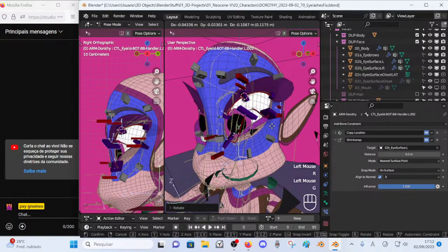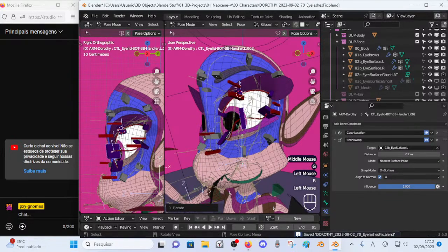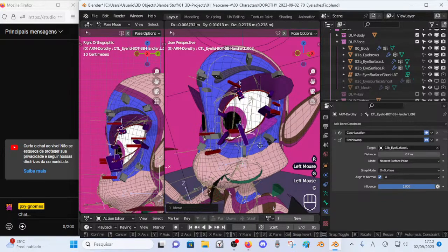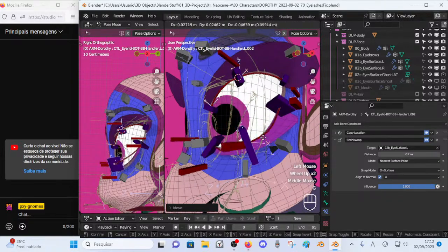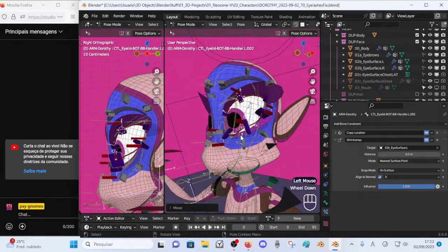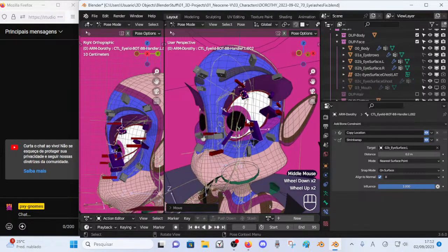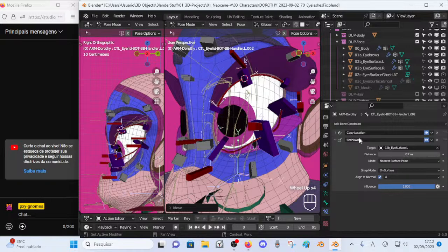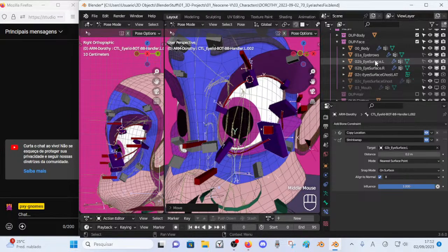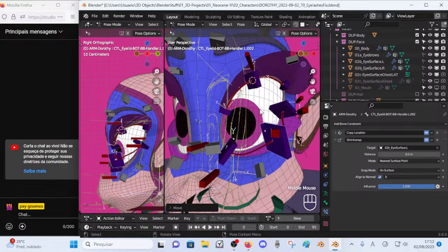But then there are some caveats, or some issues that can occur. One of them is not occurring, which is the bugging out of the other system. I think maybe Blender got improved on that matter. What we need to consider is that the eye surface mesh objects, left and right, already have meshes shrink wrapped to them, through shrink wrap modifiers.